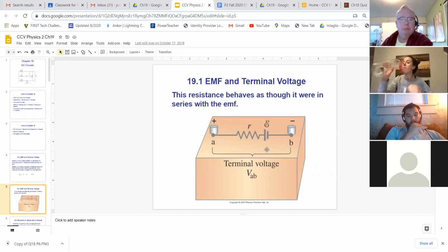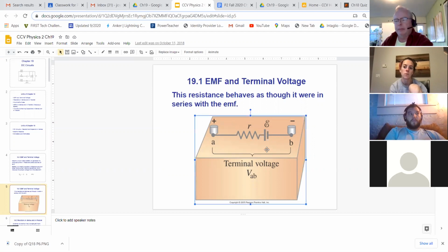Now, typically, there's not very much resistance. But over time, as reactants get used up and are turned into products, then the internal resistance increases. And that's what happens when we have a dead battery, is that the internal resistance has become so much that the chemistry is still there, but it just can't deliver the current like it used to. So it turns out that you can only test for this when the battery is under load.